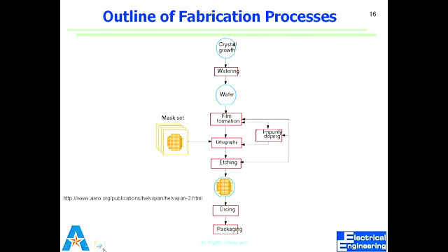So what's more common, polycrystalline or single crystalline? And what do we want to use? Common where? Industry or with what we're using? Depends on what's used, but polysilicon I can deposit in the lab. I cannot make single crystalline silicon. That requires a foundry where you can melt silicon. We'll see how we make an ingot. It's called an ingot. You have to have a pure seed of single crystalline material and you grow single crystalline silicon out of that.